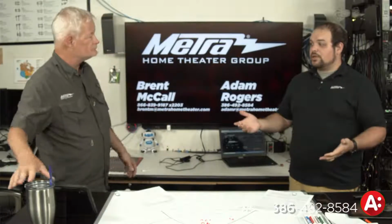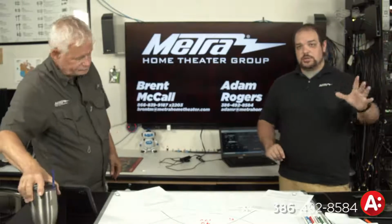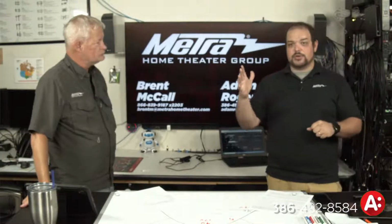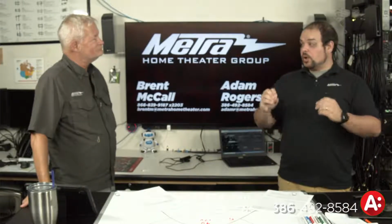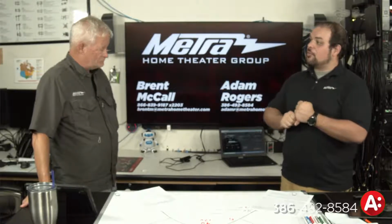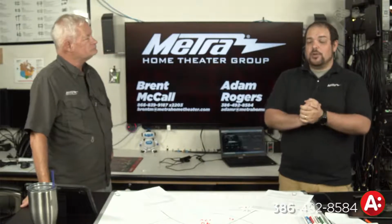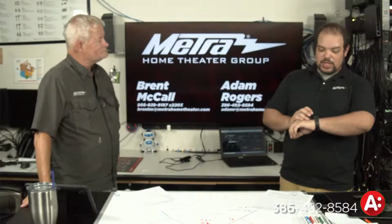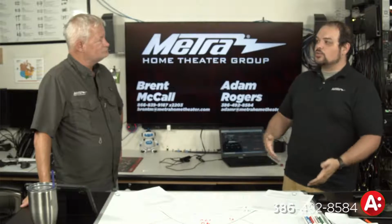So that's actually an important thing to talk about, because when you have a good cable going in between the transmit device and the receiving device, and in this case it'll be a PoE switch of some kind and a powered device, PD, you want to make sure you have good quality copper in there. So it's Cat 6A, which is a thicker gauge copper. It's got better windings inside of it, better twist ratios. And with that, what you're going to wind up with is less loss, but it means that the device that's giving power doesn't have to work so hard.